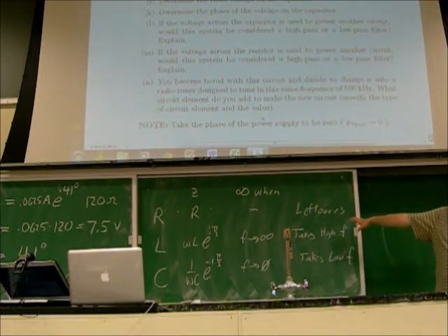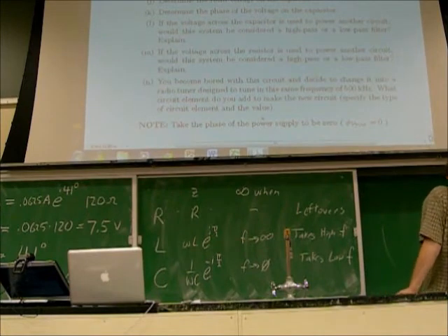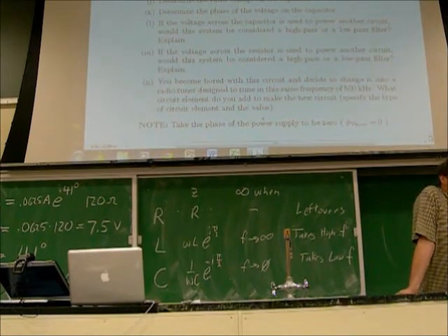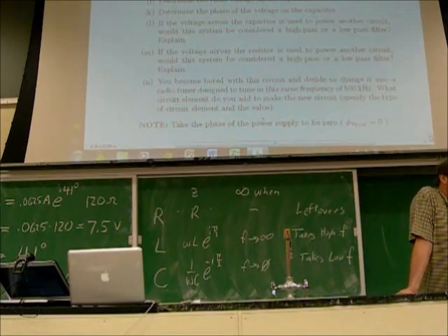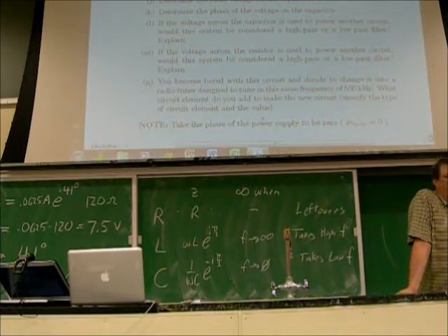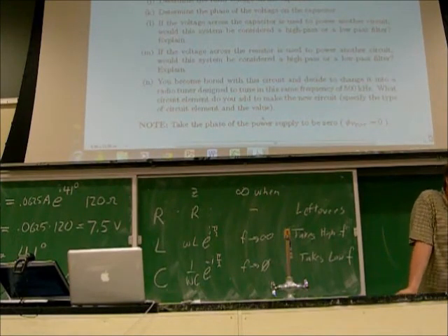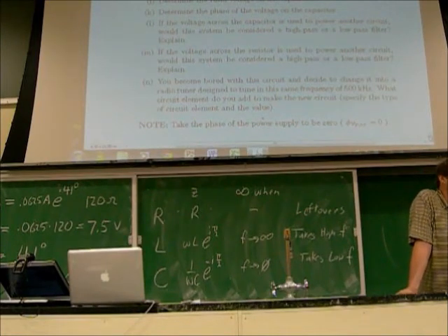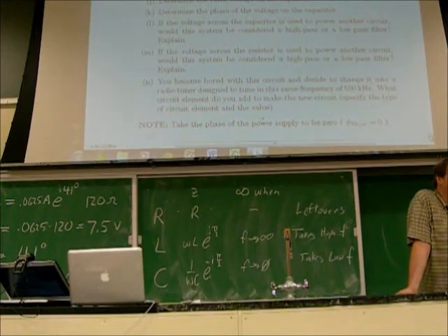Everybody follow. The other final thing is, if you look at the motherboard inside your computer, you're going to find that there is always a capacitor near every chip, because every chip expects to be running from a DC voltage. And because there are wires running all over the motherboard, and your clock frequency and you're continually accessing memory, there are fast signals going all over the place, and your DC voltages can get disturbed.